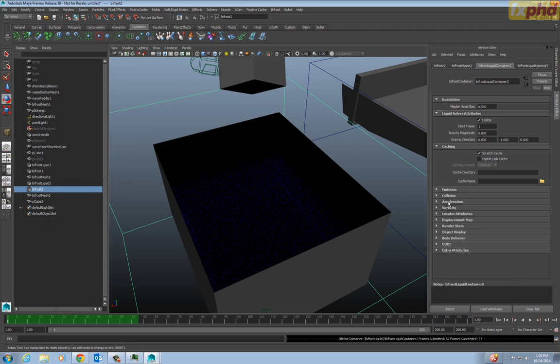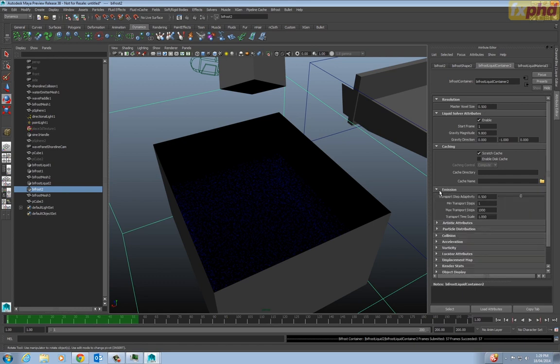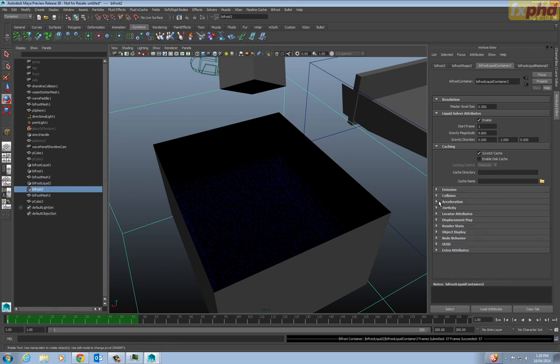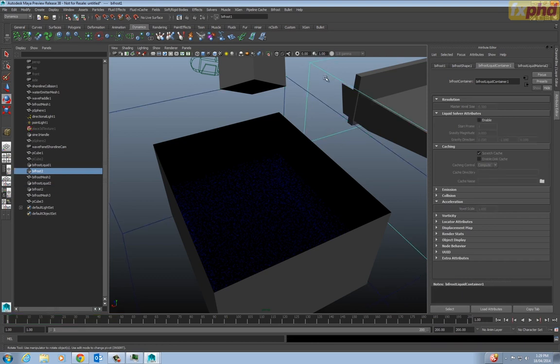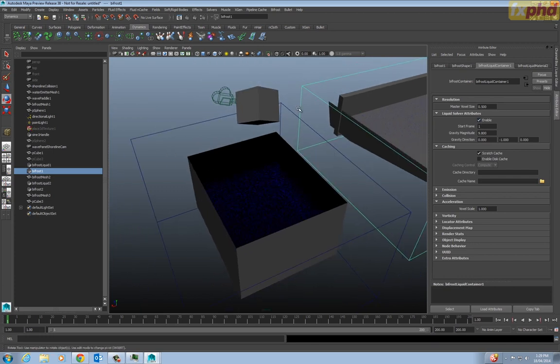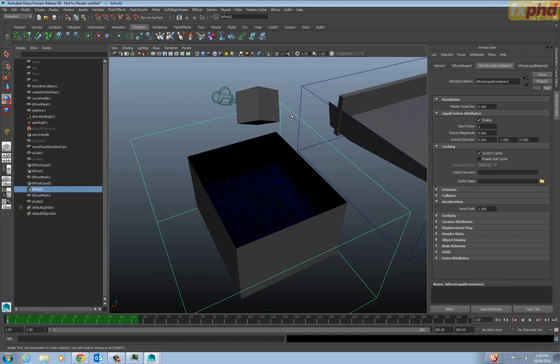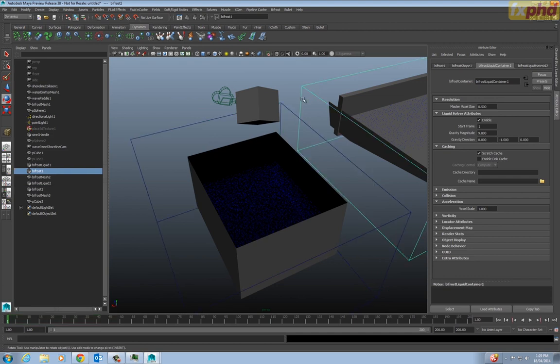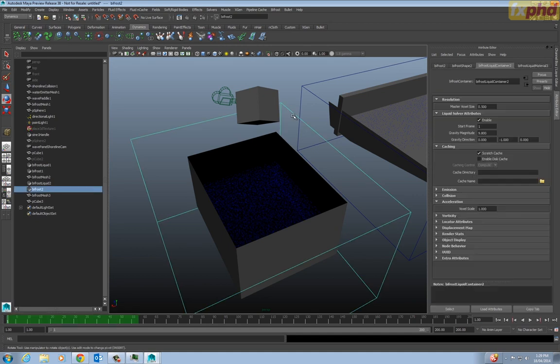If we have a look at the particle setting on here, it's not just about having billions and billions of particles. It's also about having a proper voxel size. The voxel size for the original beach simulation, it says in the little notes down the bottom, this voxel size of this sim is low for a best setting set to 0.08.